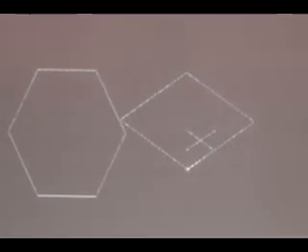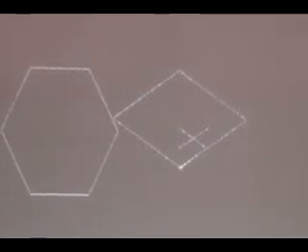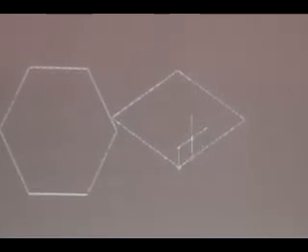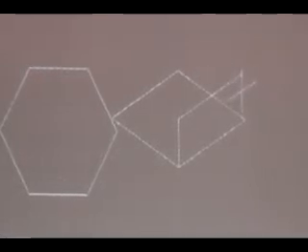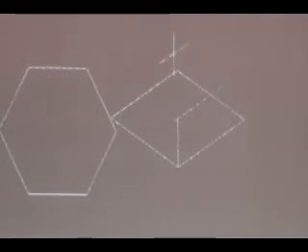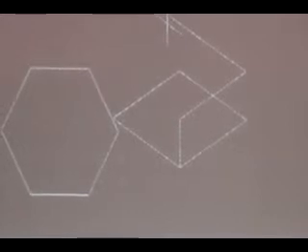Suppose I want to raise the height of the isometric view along the z-axis. So I have typed F5, and it goes to another axis, the z-axis. Along that I want to raise a height of 10 mm. I have raised it. Then along this we want to draw 20 mm, right? Then F5.